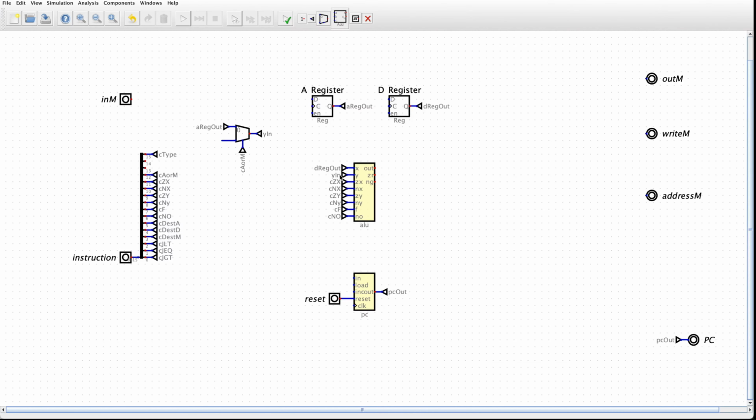All right, so we have now satisfied all the inputs to the ALU, with the asterisk that we haven't yet started indexing memory. So this is starting to come together a little bit. But what about loading Y from memory if this A or M flag is set to M? Well, we're actually given that index to memory just as an input. So we can just wire that up like that. And now, at this point, we are actually satisfying all of the inputs to the ALU. So let's start thinking about the outputs.